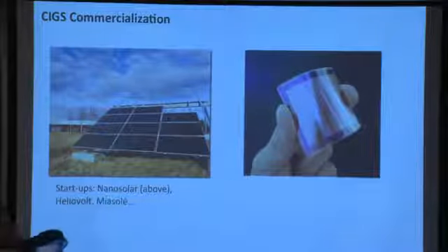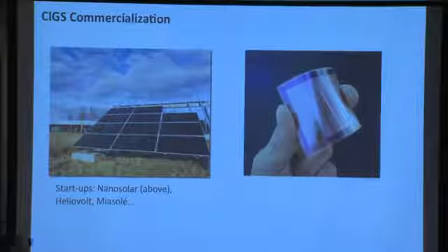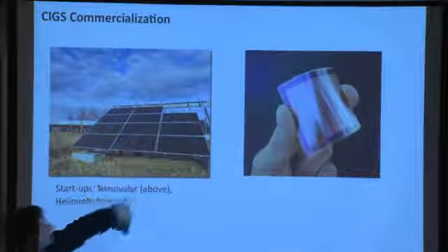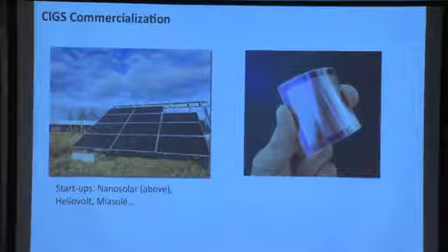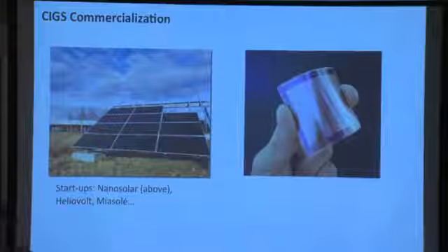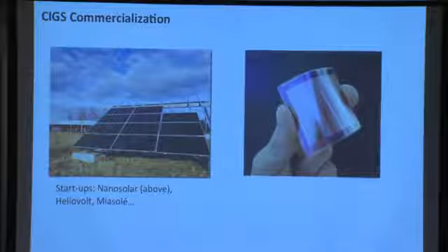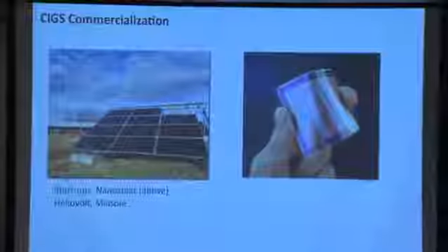This particular technology shown here, let's keep this company nameless for now, represents some of the difficulties in ramping up large area CIGS. They deposited sometimes over large areas, but would achieve inhomogeneous results. And so the ultimate form factor for the devices was to chop them up into areas not too dissimilar from an actual crystalline silicon device. So they chopped up their layers into individual discrete cells, and then connected and soldered them together, much like a crystalline silicon device would be put together inside of a module.